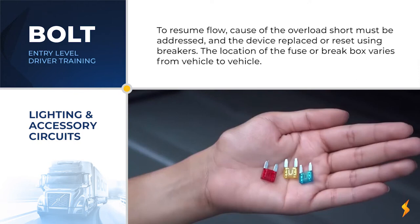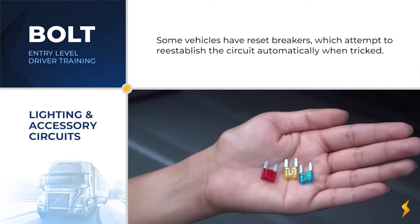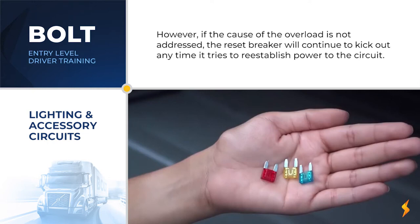To resume flow, the cause of the overload or short must be addressed, and the overload protection device replaced, if using fuses, or reset, if using breakers. The location of the fuse or breaker box varies from vehicle to vehicle. Some vehicles have reset breakers, which attempt to reestablish the circuit automatically when tripped. However, if the cause of the overload or short is not addressed, the reset breaker will continue to kick out every time it tries to reestablish power to the circuit.